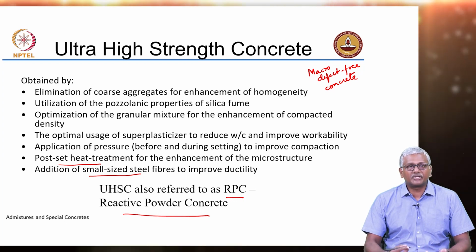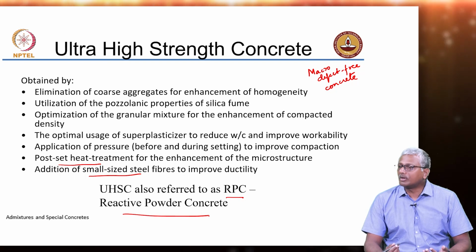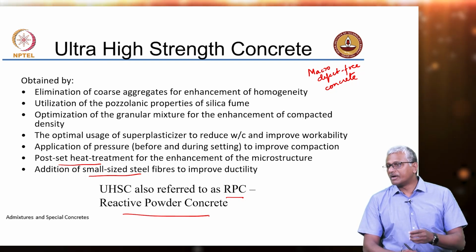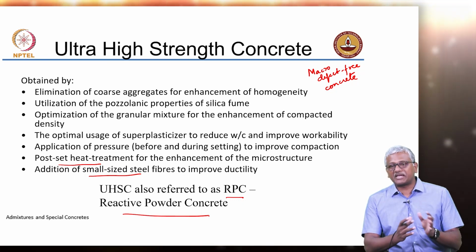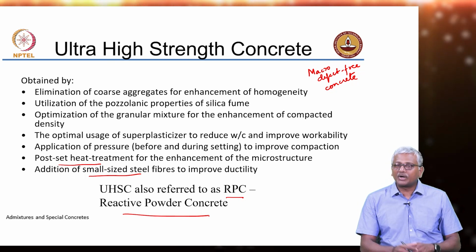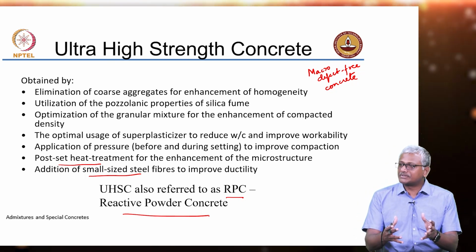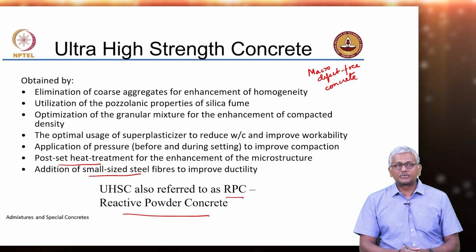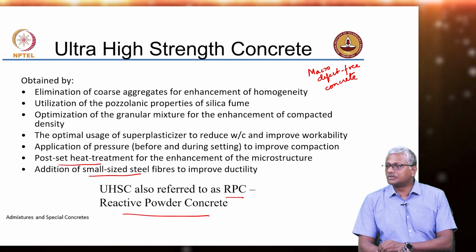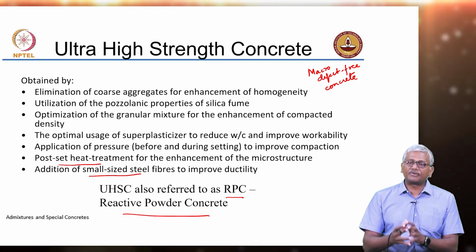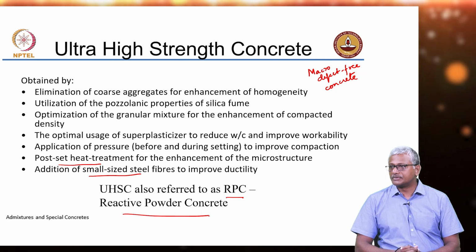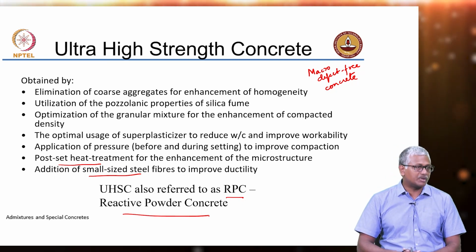Will it hydrate much? Probably not. No? It's not going to hydrate much because there is, first of all, you have so much powder in there that there is no space for the hydration to happen. But yet, obviously you can't just take the powder and compact it, no? It's not going to work. So hydration is still necessary to an extent to ensure that you have a skeletal framework that is created, which can bind the particles together. So some minimum level of hydration is absolutely important.